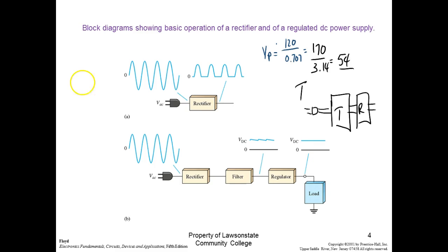So we're using what we call a 12.6 volt center tap transformer, which means we can get 2 voltages out of it. We can either get full secondary voltage or we can get 1/2 secondary voltage. And we're going to use the full thing. Now, when we're talking about this, we're talking about the output voltage, the center tap, right? You understand that? Everybody okay there? Any questions?